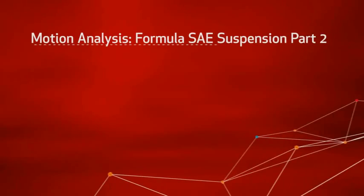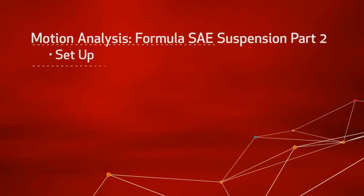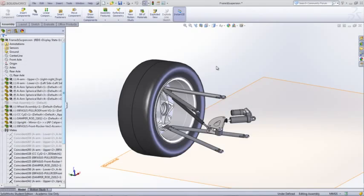This is the second part in a group of videos showing how to set up a motion analysis on a Formula SAE car's suspension system using SolidWorks Motion. In order to run the simulation correctly, it is best to simplify the model by removing any parts that do not have to do with the suspension. When simplifying, make sure that the ends of the arms are located where they would be mounted on the rest